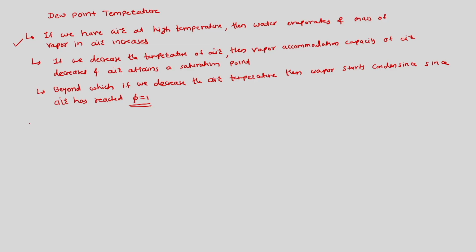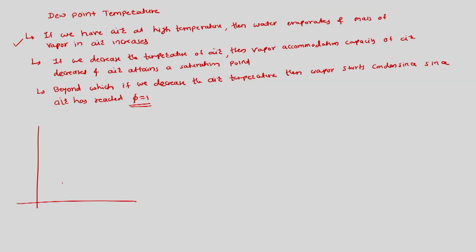So the temperature at which water vapor would start condensing upon decrement of temperature of air is called dew point temperature. So if we put it in a thermodynamic process, then we are saying that we are having water vapor at a certain superheated state, and that is in the mixture of air plus water vapor, which we are calling air. So this is the condition.